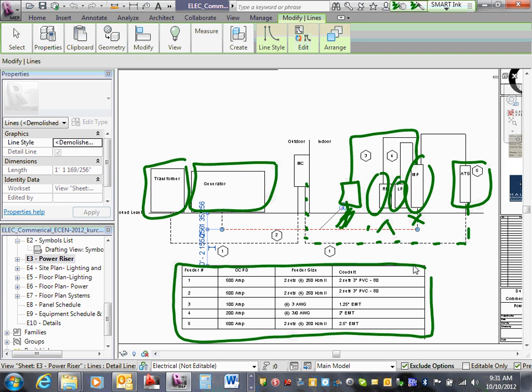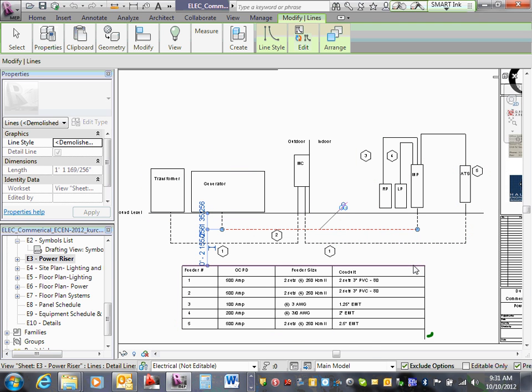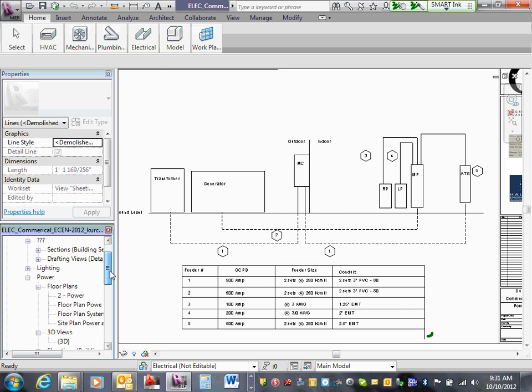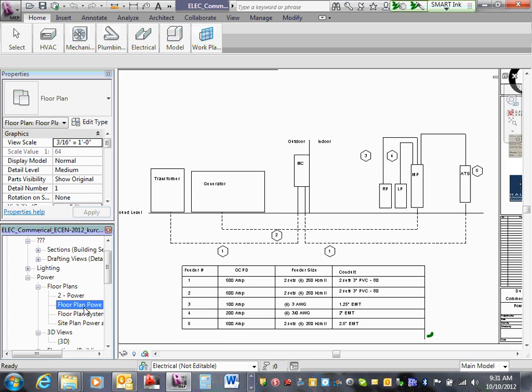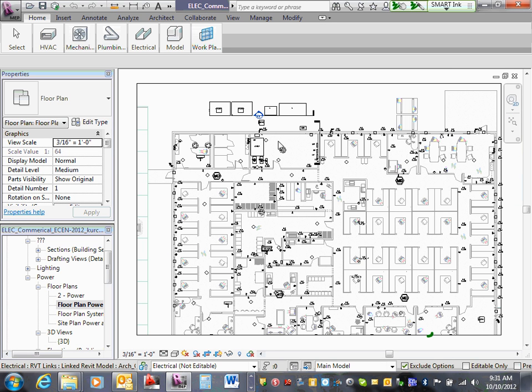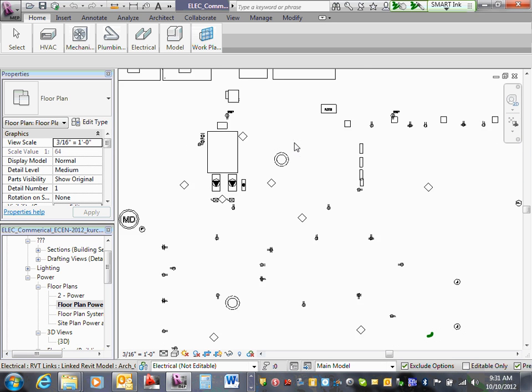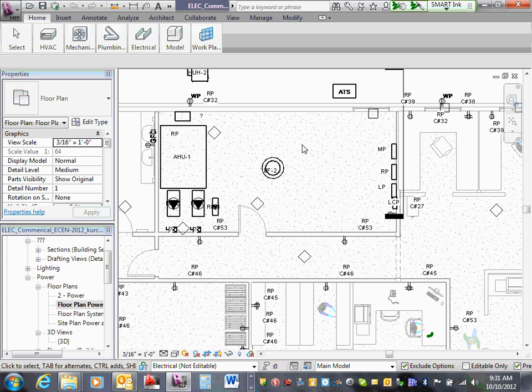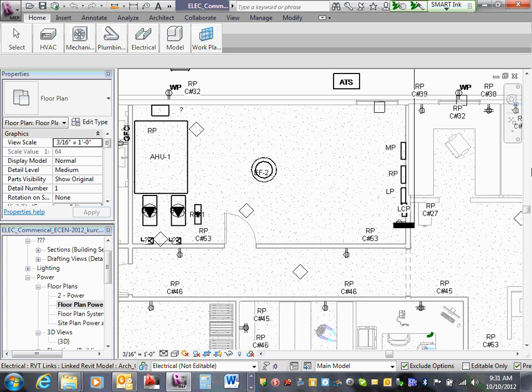The one thing I will say, the mechanical electrical room for this building, sometimes it comes up, sometimes it doesn't. One of the main things we do when we're laying out mechanical and electrical rooms, especially when they're combined, is we coordinate with a mechanical engineer. So I need to know the size of his air handling unit, so when I put my panel in, his air handling unit isn't sitting in front of it in my clearance space for 3 feet in front of the panel.